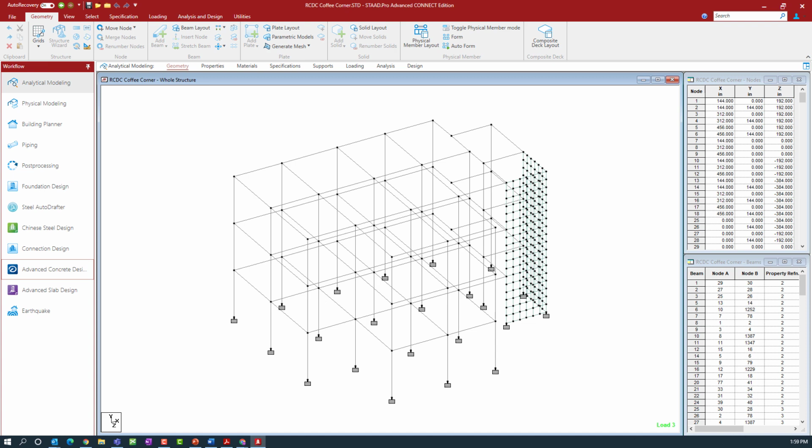Okay, there was a question: when you model a shear wall parametrically, does the program consider that element as a solid element or as a plate element? You're basically going to create it as a plate element. So you can see here I've created some parametric models. The parametric models are transferred. These are plate tools, so they're transferred as a plate, not as a solid element.